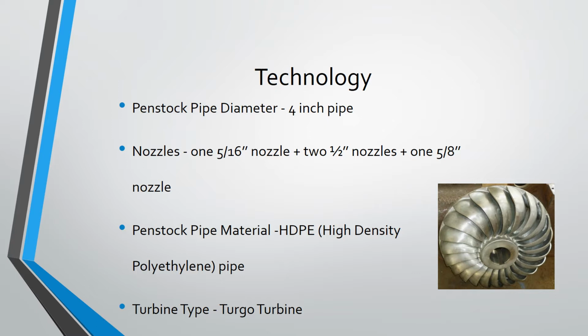Also, the HDPE pipe does not have to be buried, which will make maintenance easier and more affordable. Also, since our client is in North Carolina, there are freezing temperatures occasionally, so HDPE pipe can handle freezing temperatures and PVC pipe cannot.